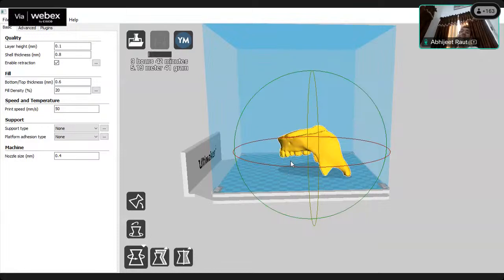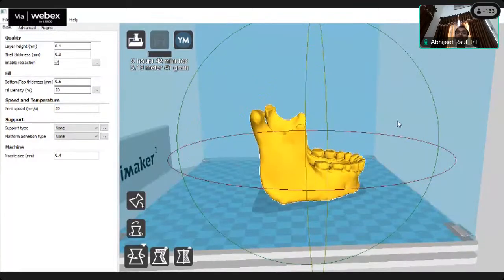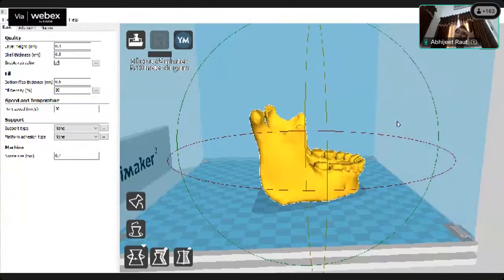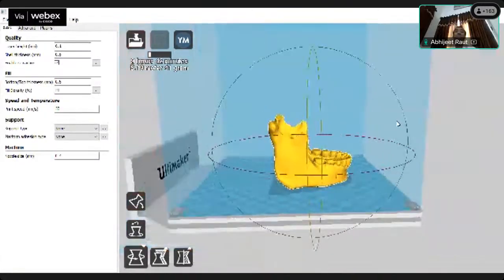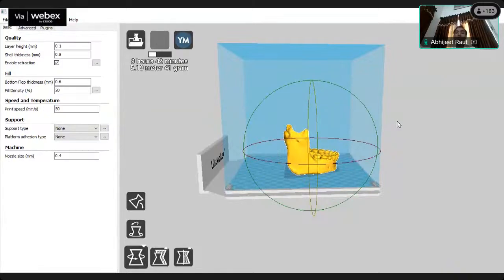And at the time of post processing, after 3D printing, we need to remove that support, and that's why the accuracy may be affected. So this orientation is very important to remember. Before 3D printing, consider the orientation, what the targeted area is, and what our requirement is. Orientation is also very important for time and material consumption, so that your support will be reduced, and ultimately time will be reduced, right?